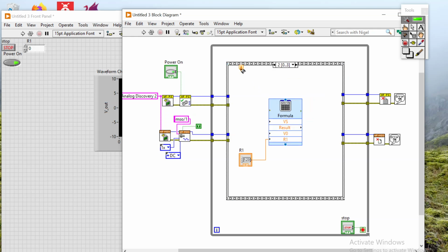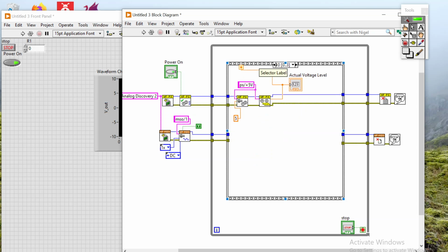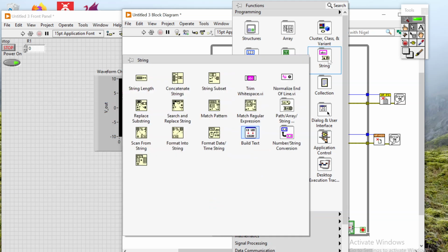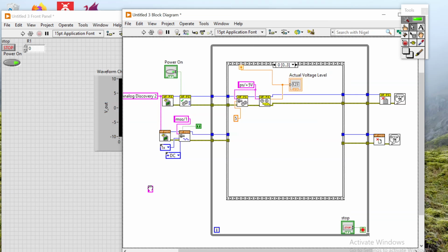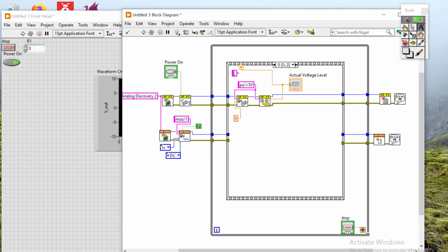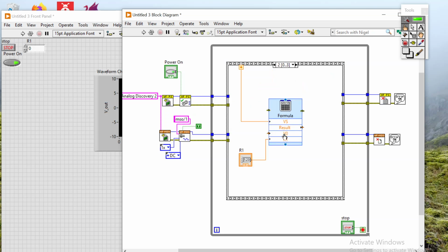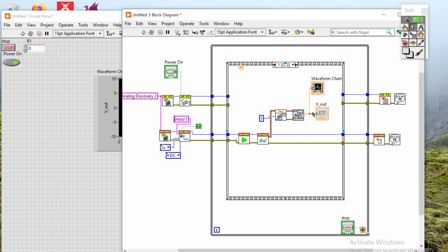Okay, so that means I can wire this. This is Vs. I can wire this to Vs. And so we remember, let's put a little label here. So I'm going to add a string constant to help me remember. This one's Vs. Okay, and now I'm going to go back here, and I need V0. That's the output voltage, that's this value.